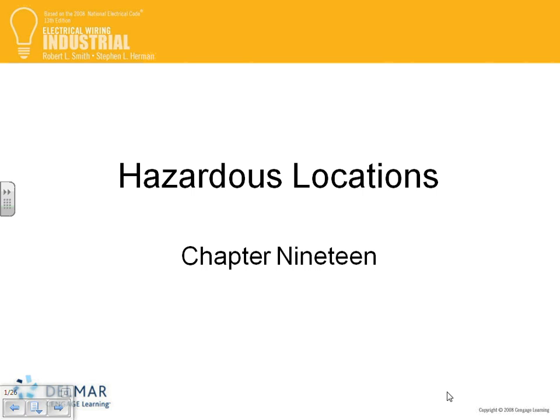Okay, if you guys look at 3-10, please highlight this one. There are three hazardous locations acknowledged by the NEC code book. Class 1, 2, and 3. We have touched on this before, guys. Everybody knows that. 1, 2, and 3. And they take the class and divide it into two divisions: Division 1 and Division 2. So the most important things to understand, guys, is what the classes are and what the divisions are.